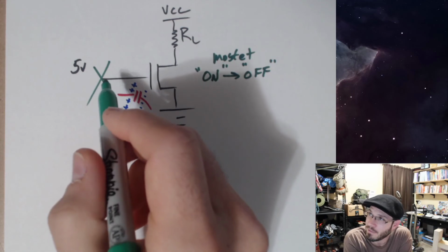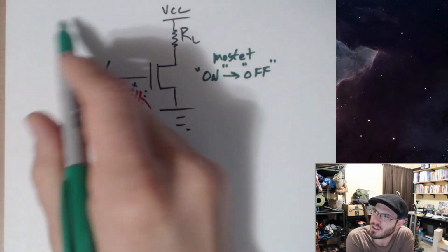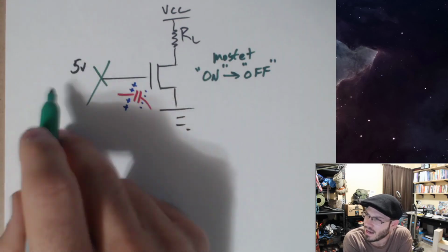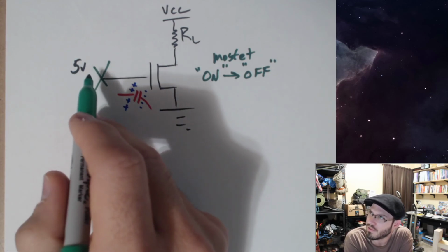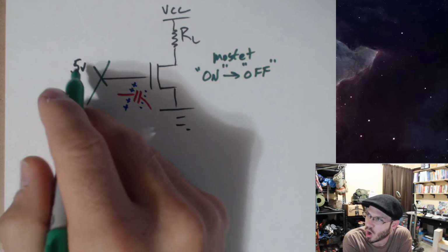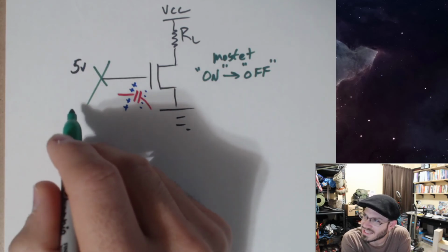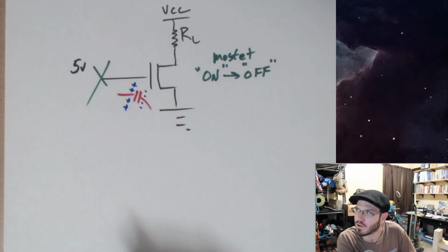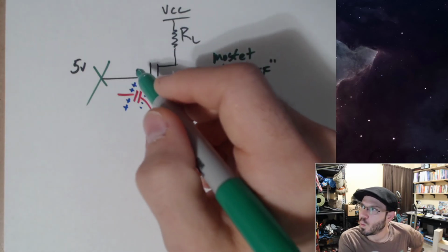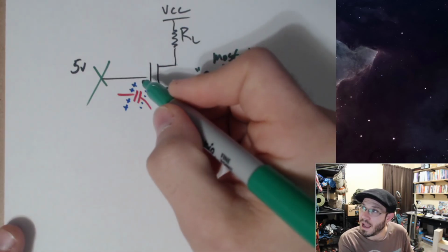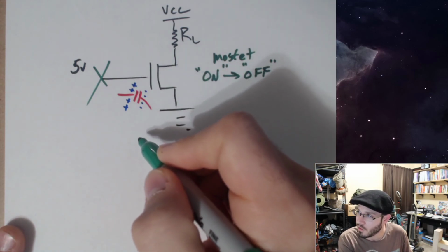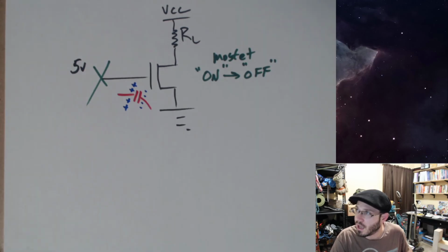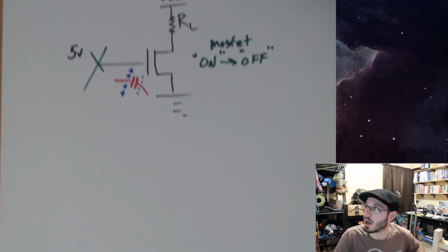And then on top of that, depending on the circuitry that's inside of the microcontroller, maybe you don't have a strong pull down network inside for some reason, then we would be well served by also putting a resistor from this input down to ground in order to give us another path to discharge.